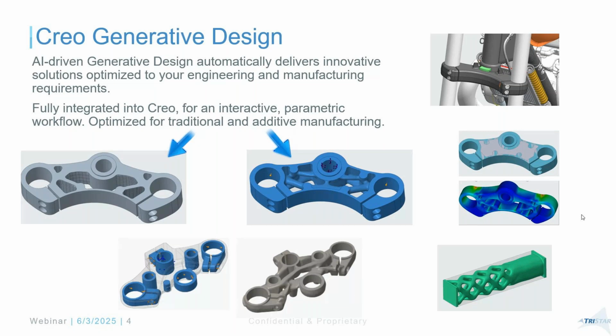You give almost like a sandbox or a solution space for your geometry, and then you're trying to use maybe a safety factor, or maybe a volume or a mass percentage as a goal. And then you're also using the AI engine that Frustum has.